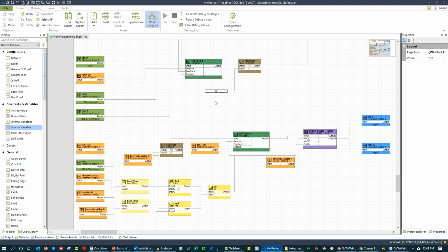That can actually be quite dangerous because you can go and make changes on live programming and literally break stuff. So I personally am a fan. I prefer build and send because I compile it, I test it, and then I send this to the program after I've tested it. And I can simulate this. I could run this in a simulated mode.